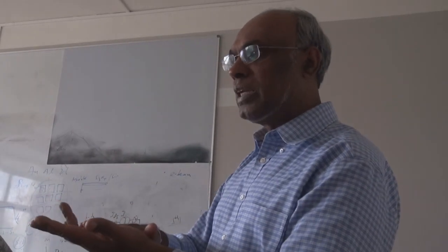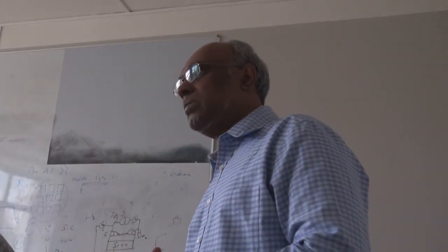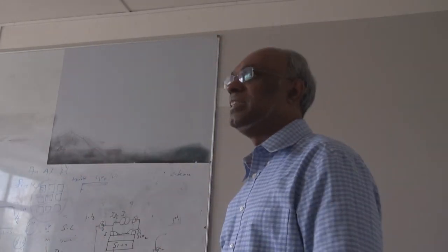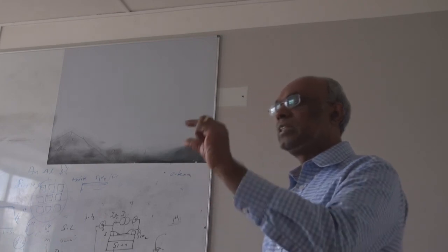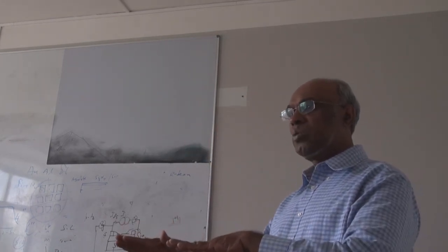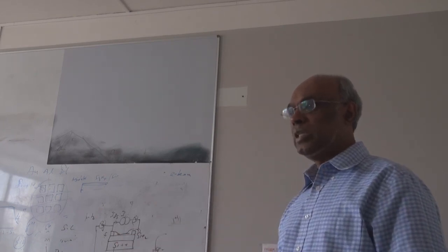Sometimes you have to do a little bit of wet etching, followed by some dry etching, using something like xenon. If you want etching from underneath, you have to do both wet and dry etching. If it is a thick sample, you have to do that. If it is surface micromachining, I think one of the etching methods is enough.